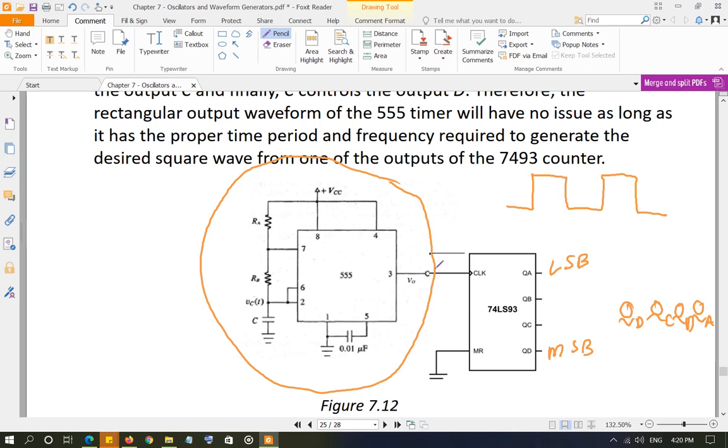Now you don't really need a square wave to run the clock, because the clock activates once per cycle, either at the positive going transition or the negative going transition of the cycle. So for example, if your 555 timer output is this, which is not a square, it will activate at either the positive going or negative going transition of the clock, once per cycle.